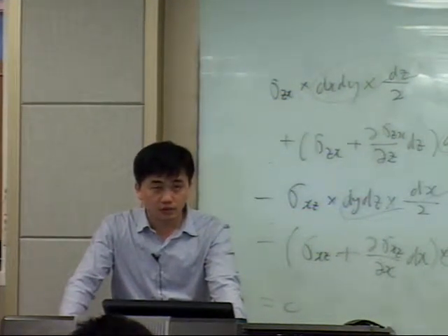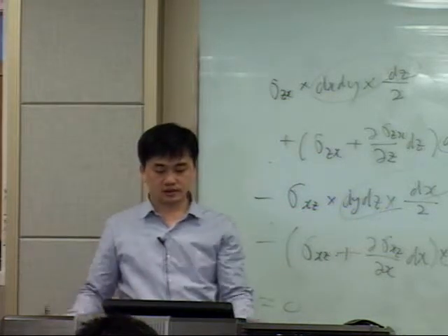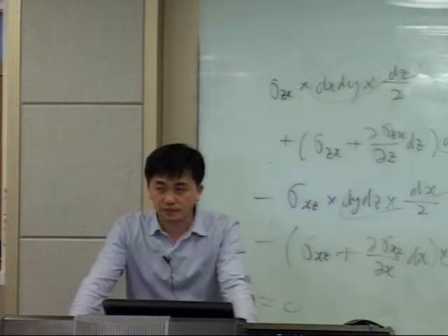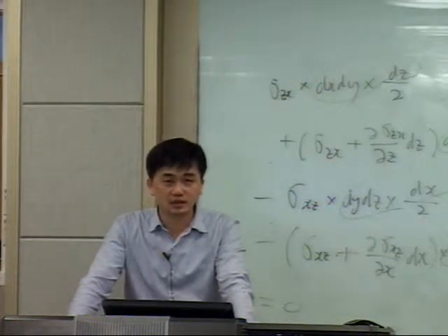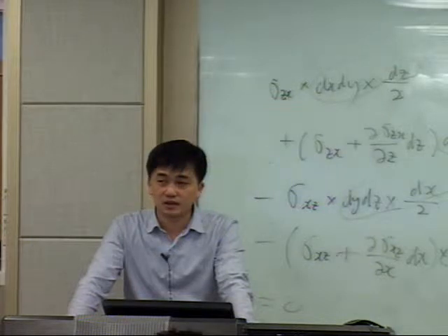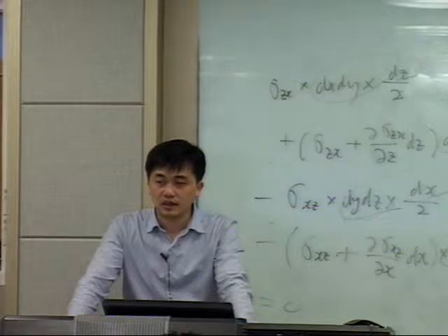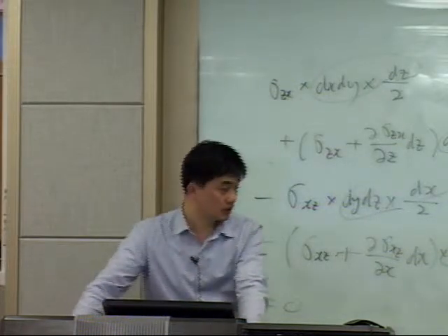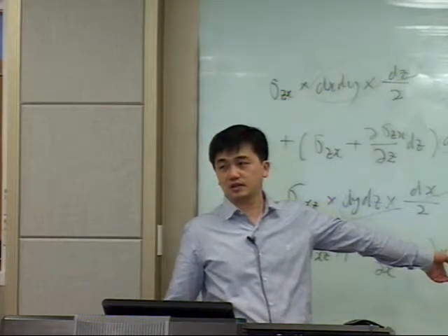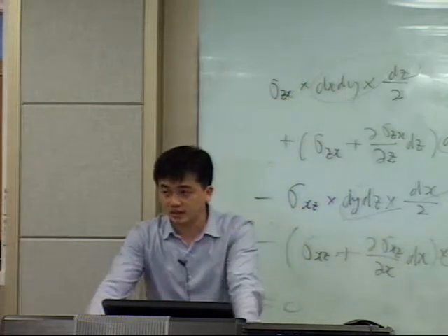So from the sum of forces equals 0, we derive the local equilibrium equation, and from the sum of the moments about the x, y, z axes, we get the property of the stress tensor, which means the stress is symmetric.